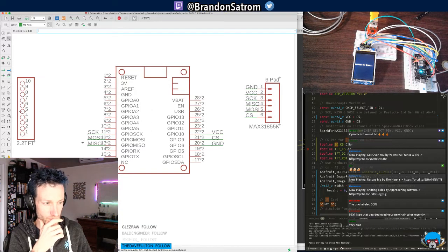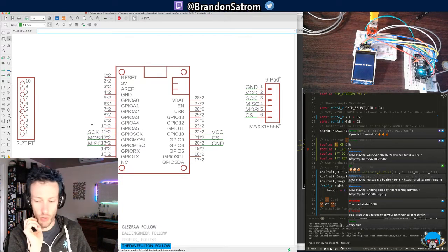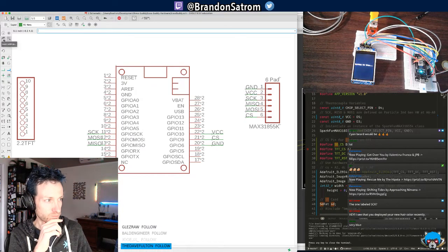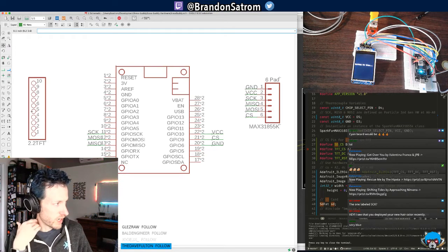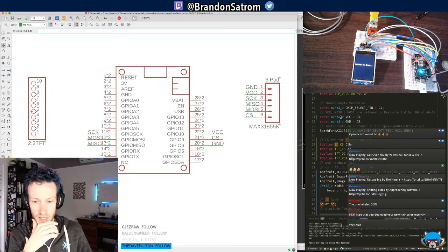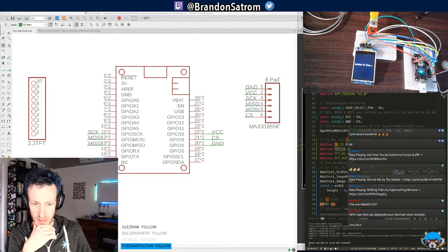Okay. So I have all 6 pins, or 6 pads, appropriately represented here on the schematic. So now it's time to mess with this TFT, which should be good fun. So I have a few common pieces here on the TFT. I am also using the A6 through A8, but then for chip select I'm using A2, A1, and reset is A0.